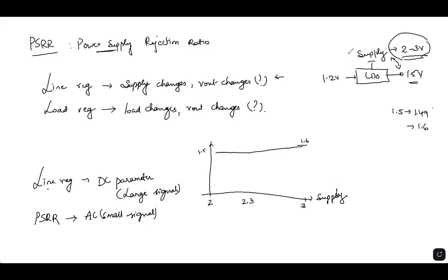The supply typically goes to a lot of places. It may be an LDO, it could be going to an oscillator, it could be going to highly switching circuits, it could be going to some PLL, it could be going to ADCs. When it goes to a lot of places, all those noise and current consumptions from various blocks are affecting your voltage node here. Just keep in mind that any voltage source will have a resistor, right? Now, this is the point you tap for your LDO.